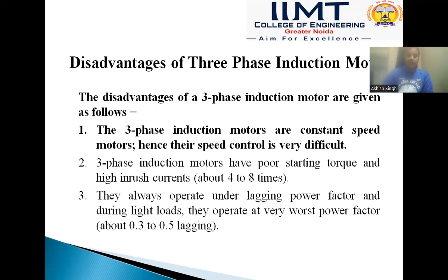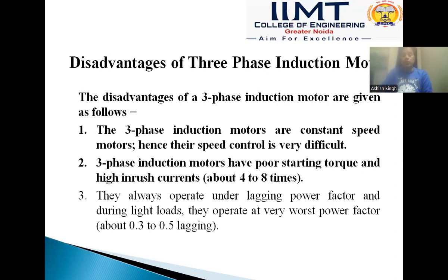Another disadvantage is that three-phase induction motors have poor starting torque and high inrush current. What is inrush current? At the time of starting an induction motor, the current drawn by the motor is called inrush current, and it is generally 4 to 8 times the full load rated current.